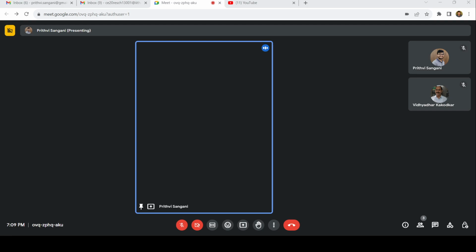I'll take moment at C. So it should be 10 times 4 plus 20 times 2, divided by 6. That is 40, 40, 80. 80 by 6? Sorry, it's 4. So 80 by 4 is 20 kilonewtons.